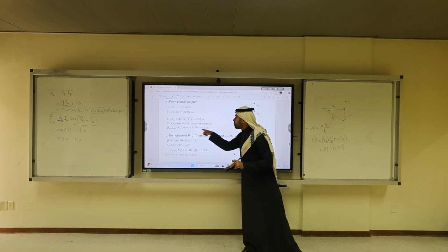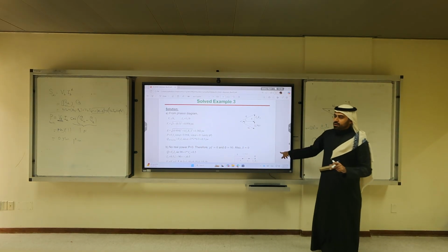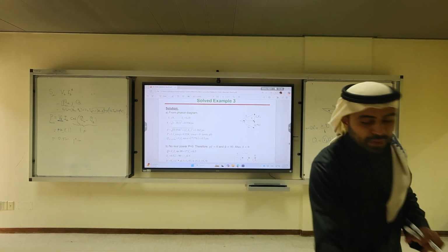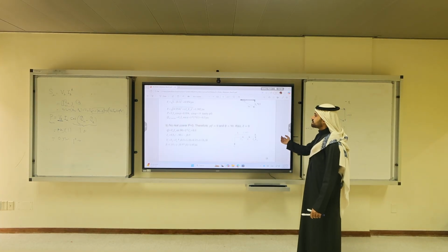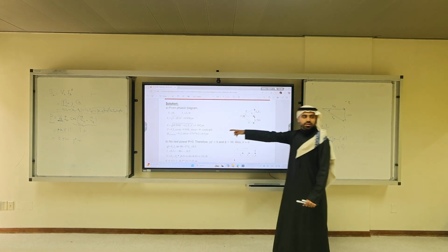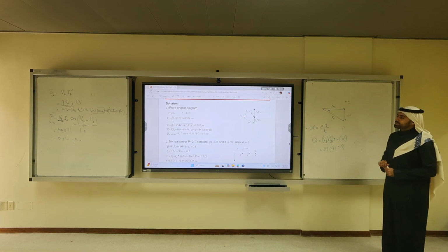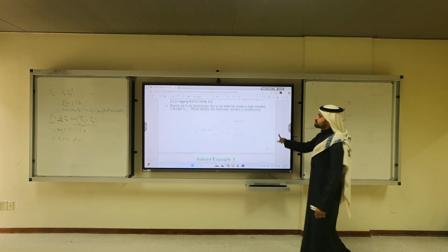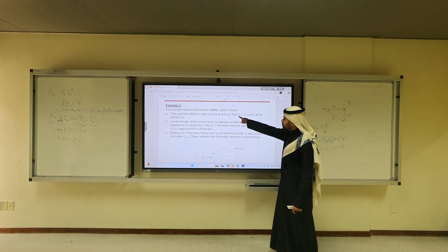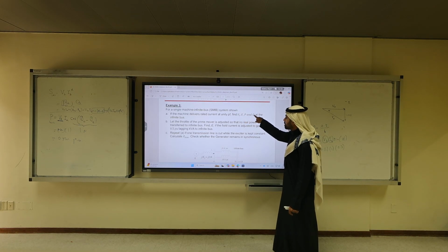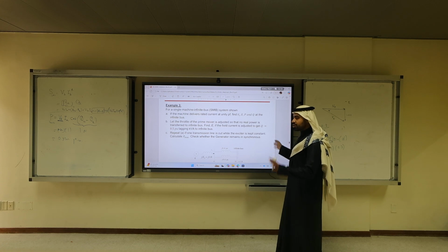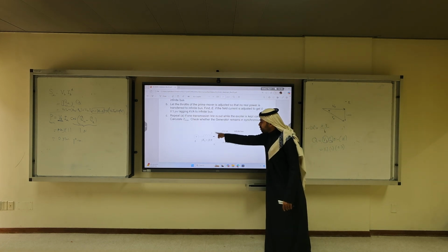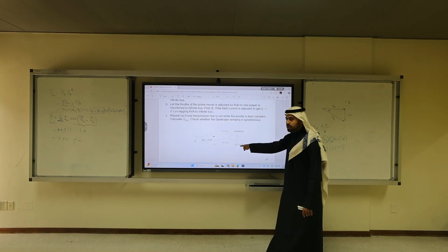So Q here is what? 0.3 period. This is not easy. The problem here is you are dealing with two different angles, two different references. One reference is for the transmission line, one reference is the terminal of the generator. So we finished part A. We calculated the terminal voltage of the generator, the excitation voltage of the generator, the real and reactive power at the infinite bus. And I told you that if you do the calculation to get Q for Vt, it will never equal Q at the B side.